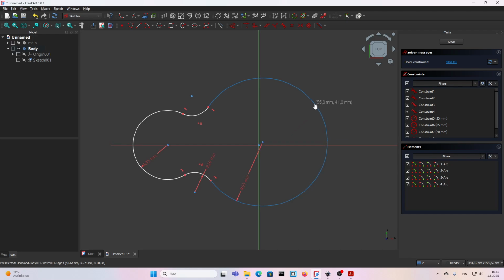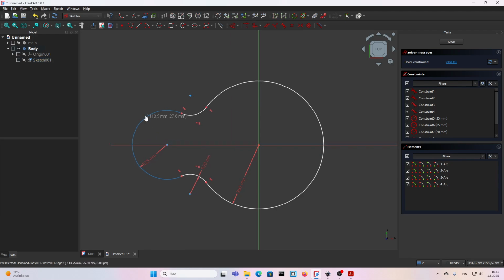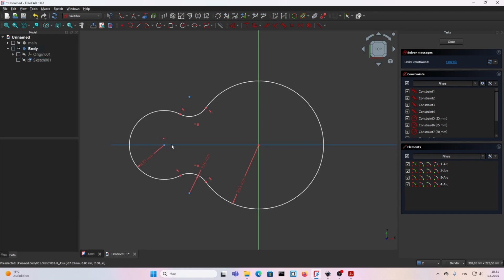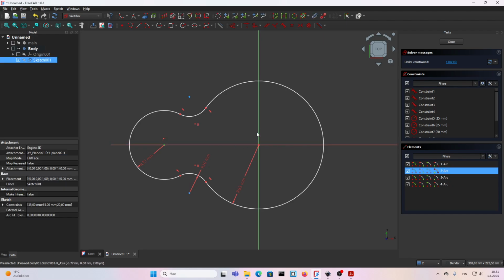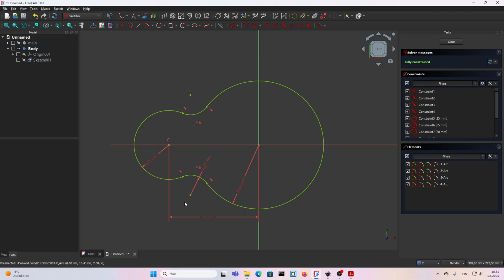Again, if I move this, it's not constrained, so these two, C from the keyboard, constrain them. If I move this, they are not constrained. Choose this and this. See from the keyboard they are constrained. The dimension is 90. And remember your constraints, keep them on this side because I will trim this side later. I'm just showing you what happens when you have a closed wire and you try to do a path array on a closed wire. Close this.